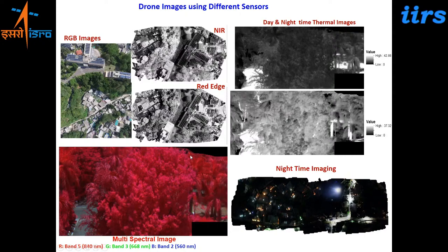So you can do a 3D reconstruction, generate bare earth information, and extract various thematic information from here, right? This is the kind of product which we can produce. You have an ortho image, the relief map, 3D perspective view, thematic layers, and the elevation model. So this is one example. We'll start showing you very quickly a few of the examples which we did here.